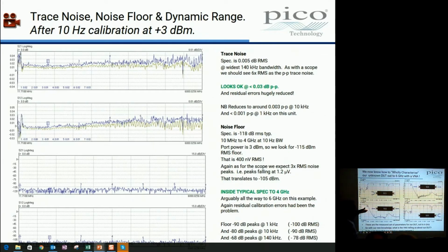It is a reciprocal device. I know there are some small differences down in the noise floor here, but it is a reciprocal passive device. And S22 is very similar, but it is slightly different. S22 is slightly different. We now know this to be the low-pass filter that we thought it was.